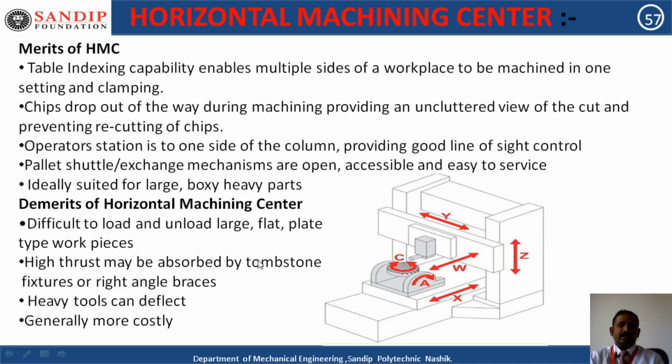And some disadvantages: it is difficult to load and unload large workpieces. High thrust may be absorbed by a tombstone fixture or right angle braces. Heavy tools can deflect, and it is generally more costly. So these are the disadvantages.